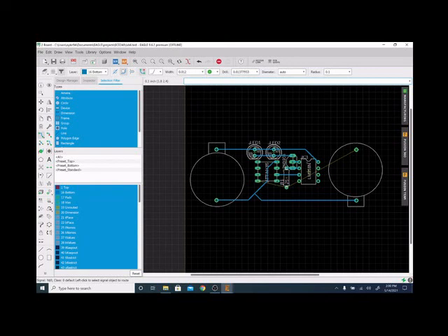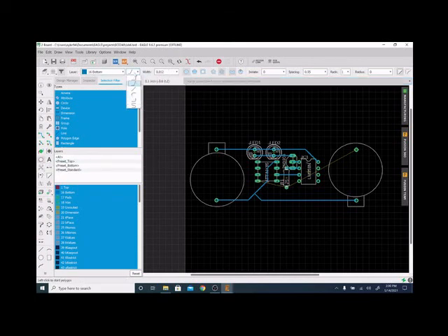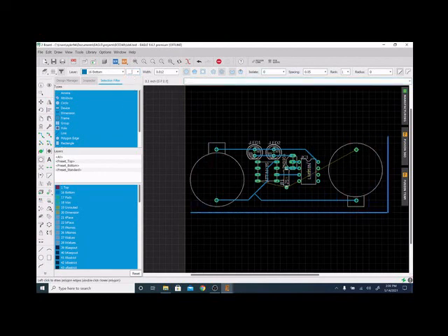So if you have it next to the ground wire or ground plane, that acts in a capacitive role to decrease the noise on that signal. It's not perfect, but it really helps. So if you notice, I've routed everything except for that ground trace. What I'm going to do now is use the polygon tool, and I'm going to change this to a 90-degree angle, and I'm going to lay this ground plane.